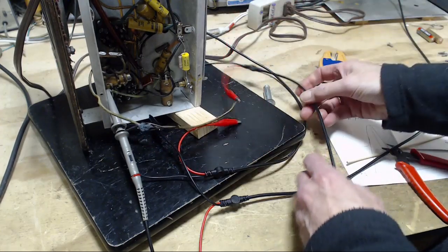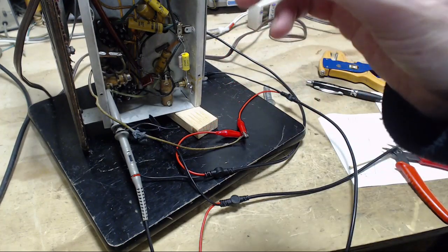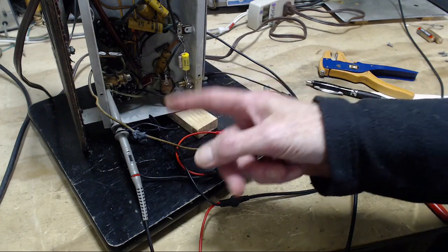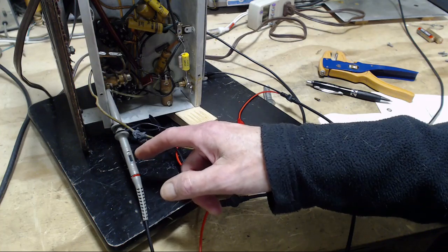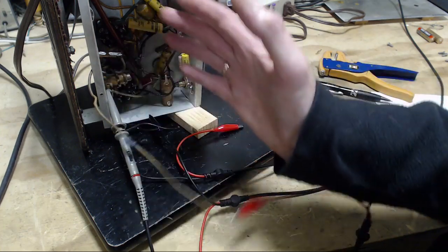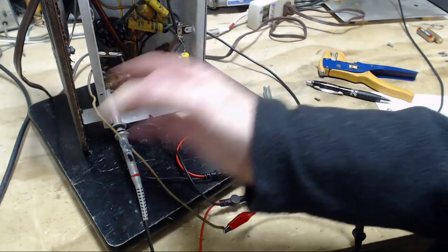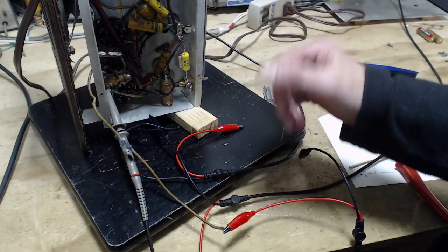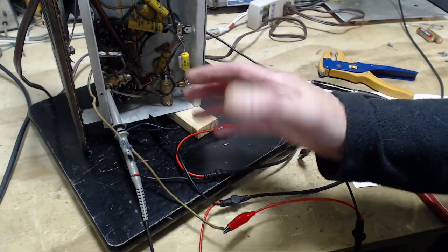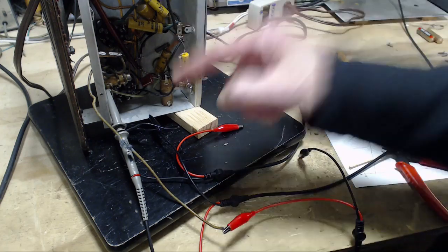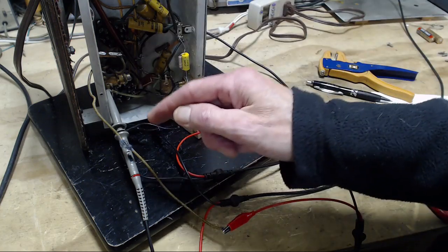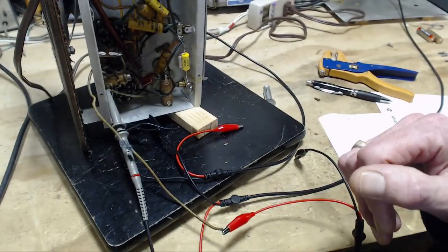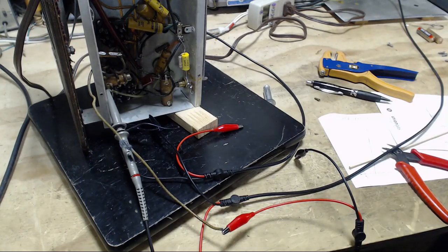Okay, so what that tells me quite clearly is there's hardly any retuning effect as long as I keep my probe at a high impedance setting, the times 10 setting here. If I put it on a times 1 setting, it's pretty obvious the radio retuned. The resonance point went off, and goodbye to the signal. It detuned the front end of the radio. So we're good. All indications are this is a valid connection. We can watch the front end on the scope for what kind of signals are in it.